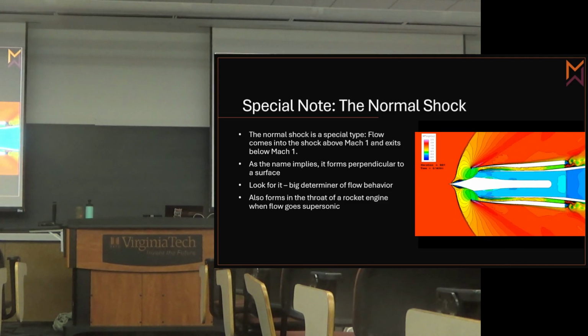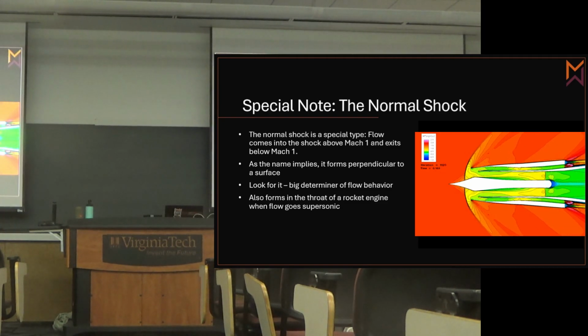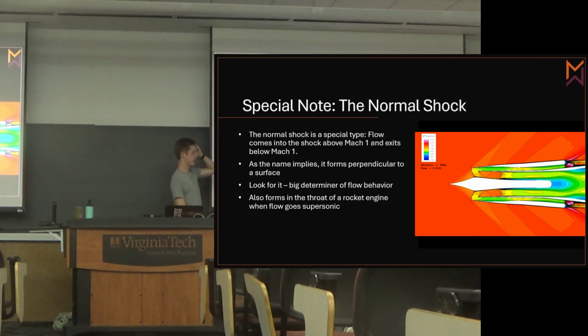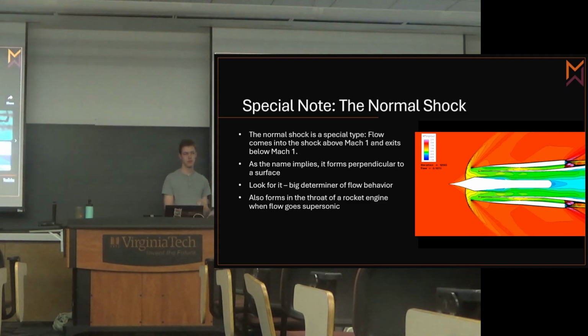And it's super powerful because it's going to take the flow that's already well past the speed of sound and decelerate it all the way down to subsonic, because it has to, because these regions have to have no flow in them, since it would be blocked. Once you open it and flow can actually continue to move, then you can make it so there is no normal shock. And this is a special case. This is called buzz, which is a pretty active topic under research. When this happens, this is actually playing through time, and the normal shocks are going back and forth, and the shock waves are changing, causing it to buzz.